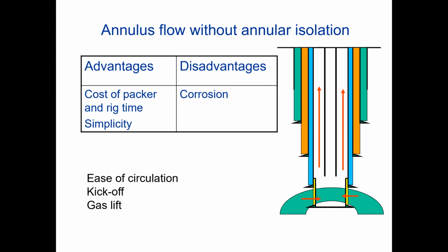As I said, I've seen places that use the annulus as a flow conduit, but it's not recommended because you will cause corrosion and erosion.